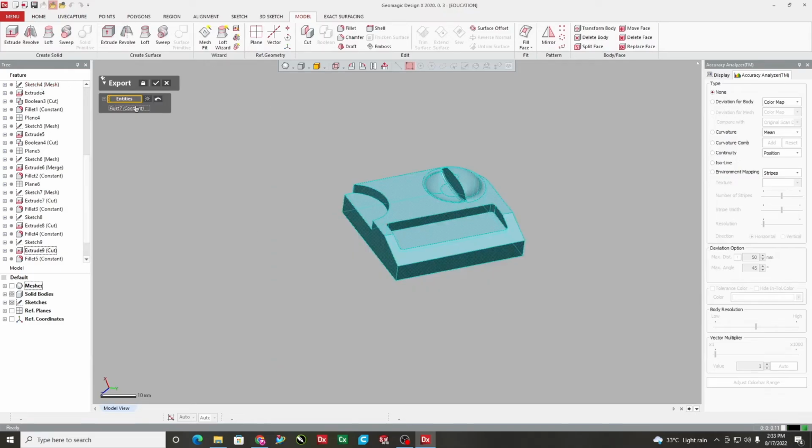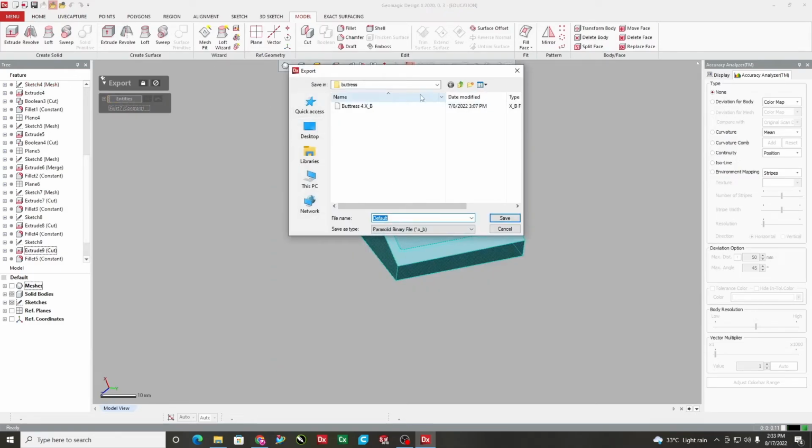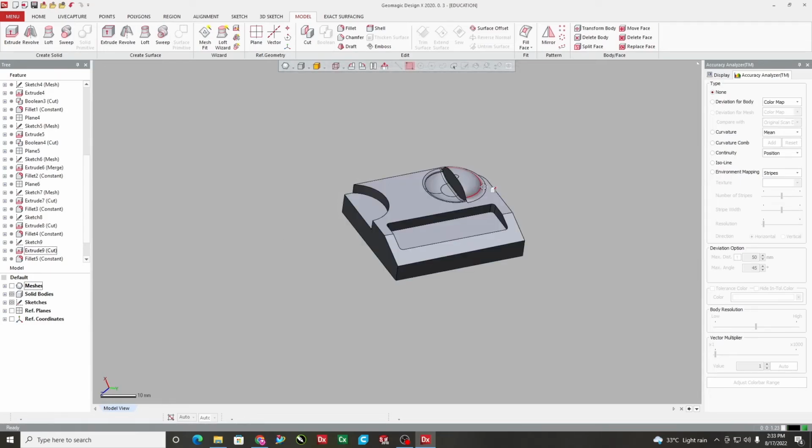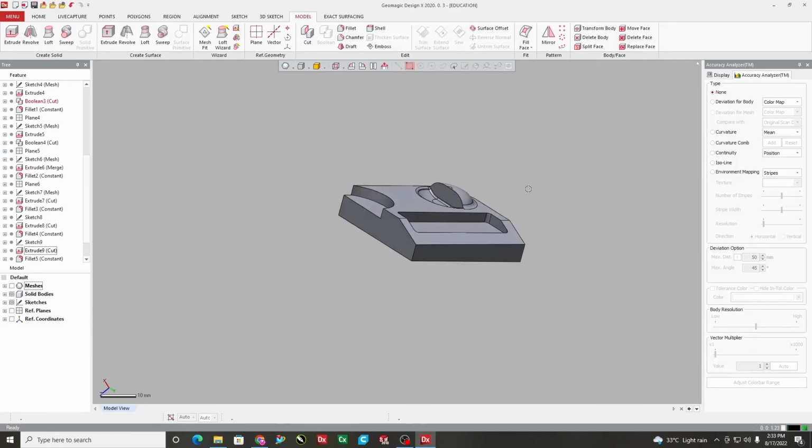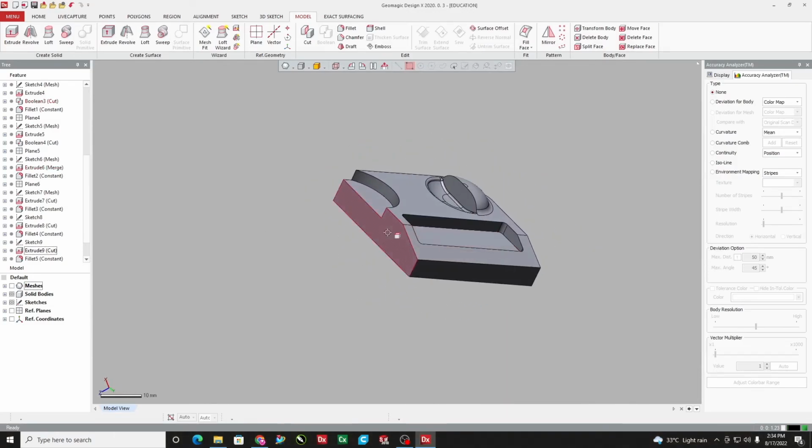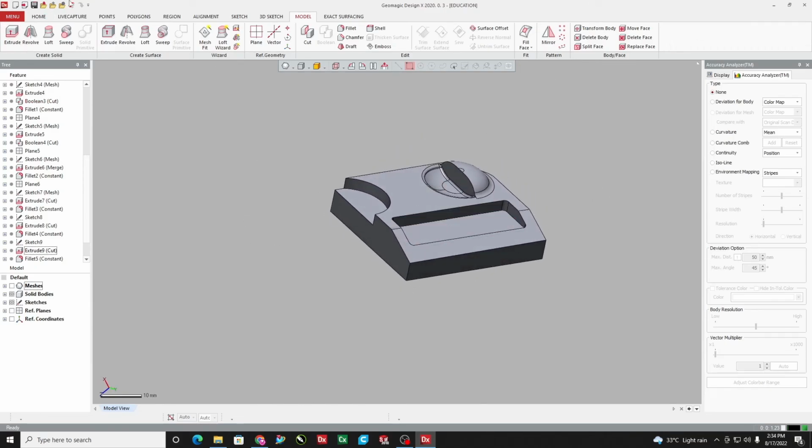Just to show you what kind of challenges could come when we try to obtain the data, we have selected this model here. Now we are trying to save this model. It could be saved in any of these formats, as STEP format or so, and it is being saved in the IGES format. It is being named as class specimen IGES. As per requirement, it is saved. In this way, we have obtained the solid model, which is close to the mesh model that we generated.